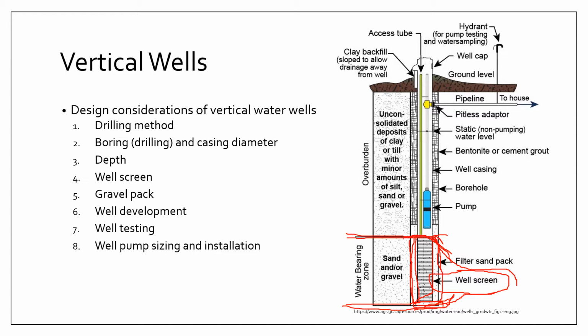And another consideration is what we call well development. Well development is just the process of more or less cleaning up your well. After constructing your well, this will typically involve drilling muds, as well as fines that are circulated around the hole that might get plastered around your aquifer formation.